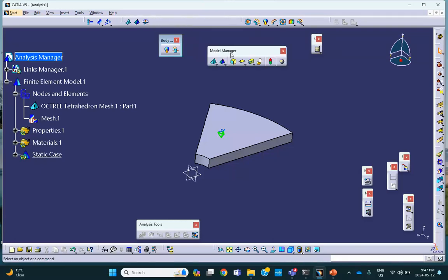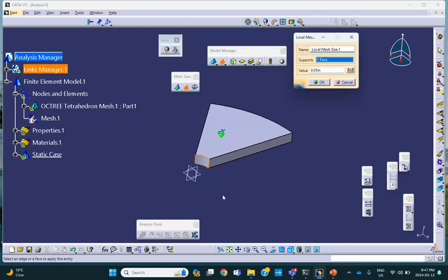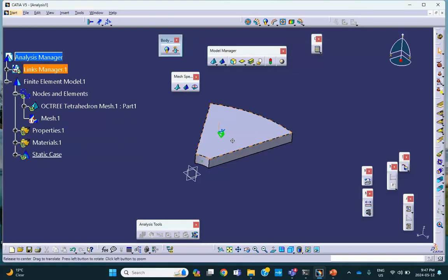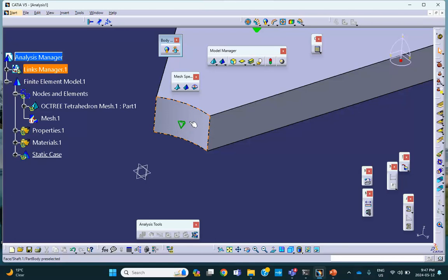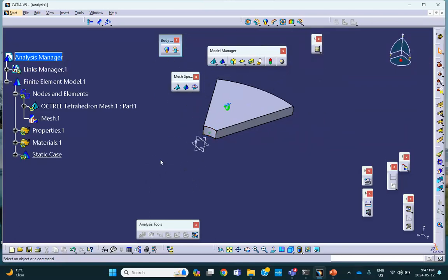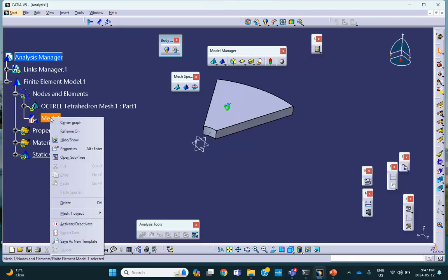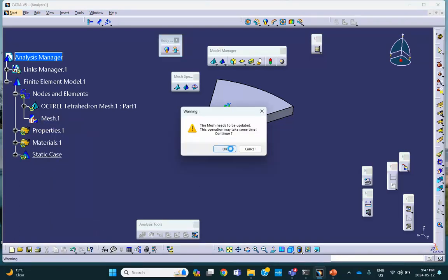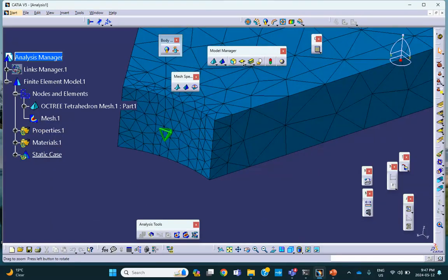in the tool model manager, the second icon is made of these three possibilities, three icons, and this one is the local mesh size. So you click on it, and it says where. So I want there, and I want a size. Let me see now. Let me make this thing 0.1. See how it looks like. In fact, if you zoom in, you can see it's sitting right there. If it's too big or too small, etc., you can make the appropriate changes. That's fine. Right click, activate, and it's going to be a finer mesh in this area. You can see that. Okay, very good.